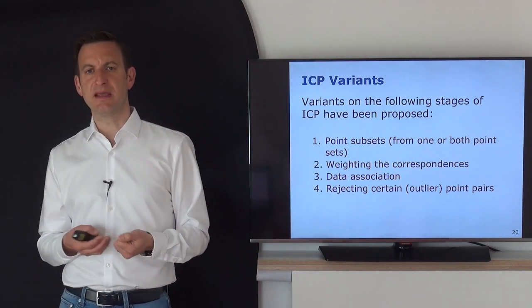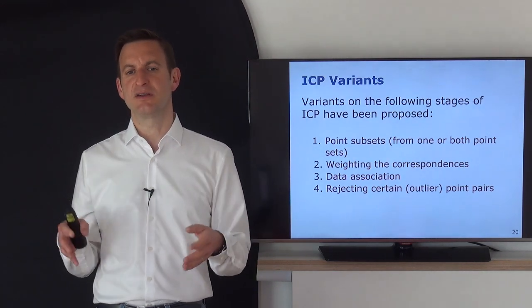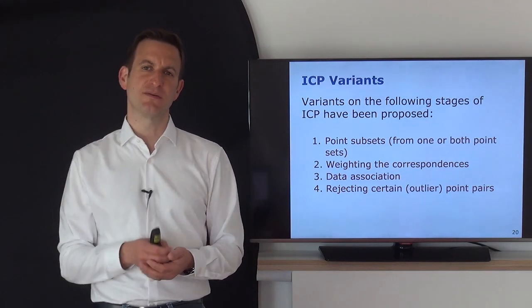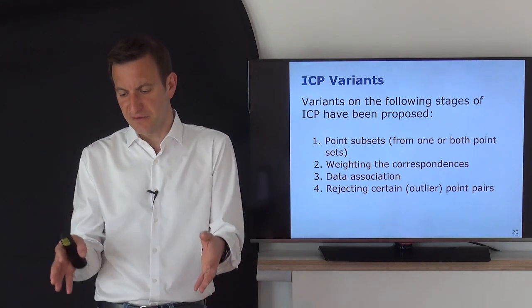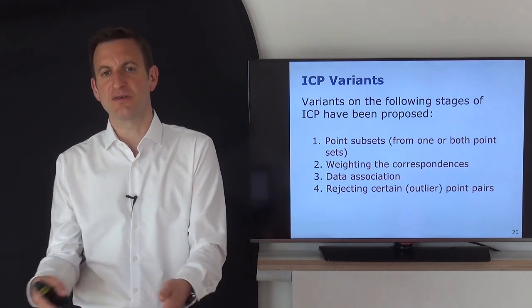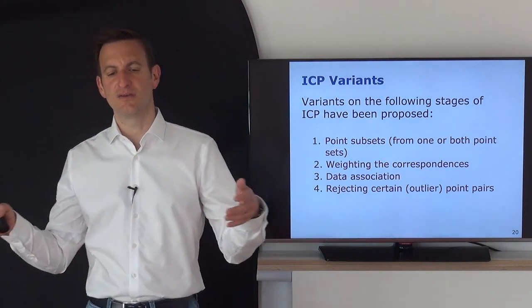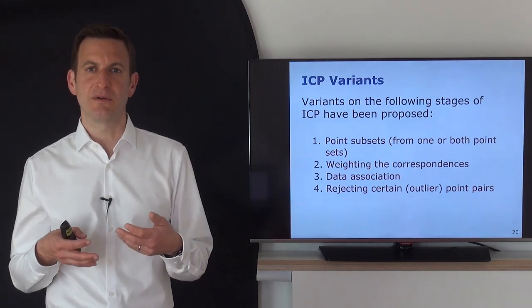So if I think about a typical laser range scan scanning points in the environment, points which are nearby will give a higher density than points which are further away. And I may not want to give the surfaces in my near surroundings a higher weight just because there are more points on the surface because of the properties of this. So this may be a reason, for example, to consider only a subset of points, for example, a uniform subset.